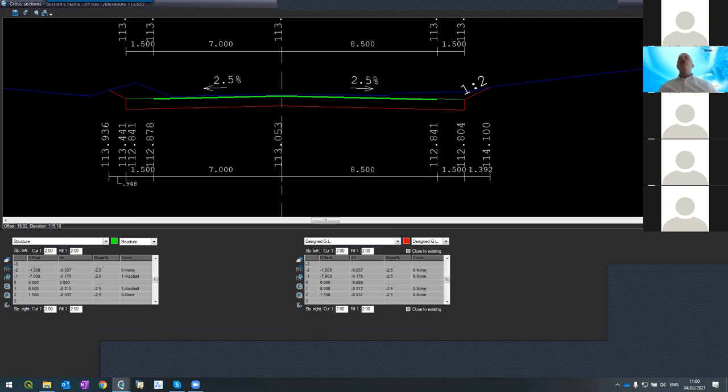How can I project it from 100 to, we said 225, to here, until here? I have two options. I can copy and go one by one and paste. This is one option. I can do it faster. How do I do it? I'm going to the segment which I changed. This is segment 1. I'm standing on it, left click. Then I'm using right click at the mouse.